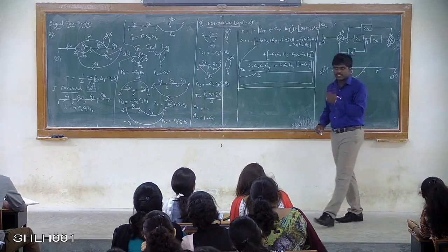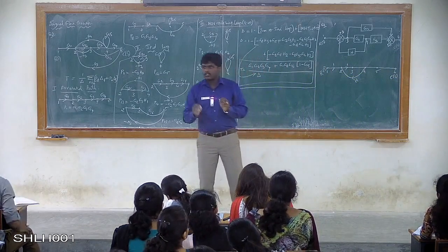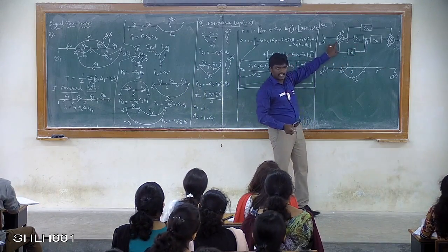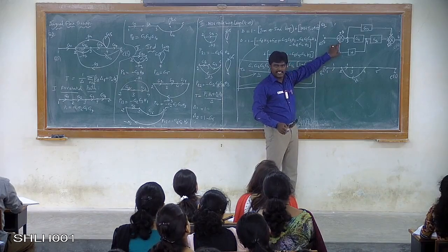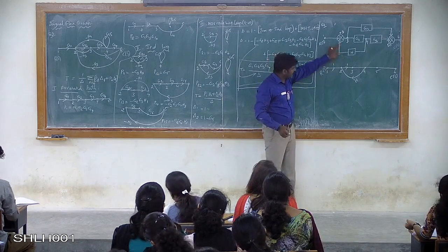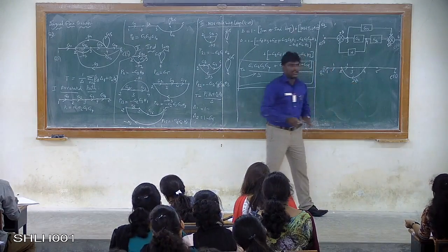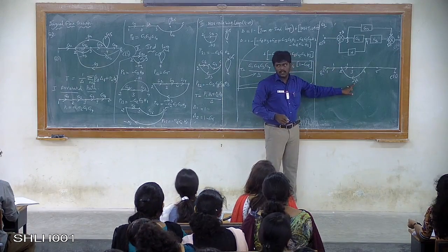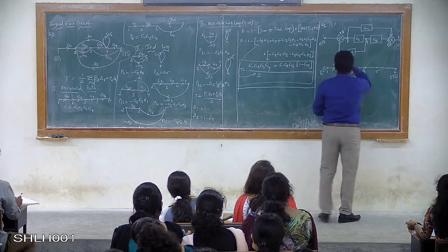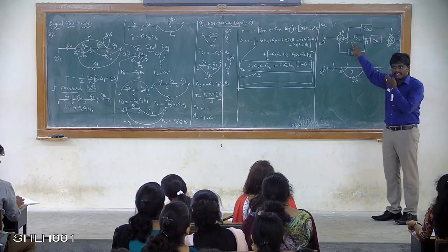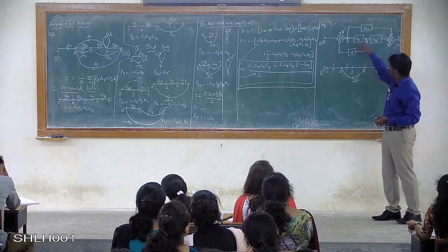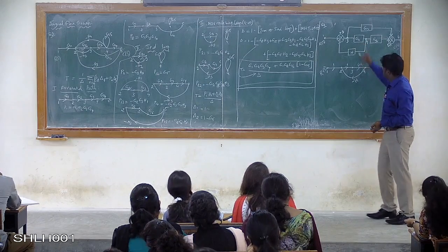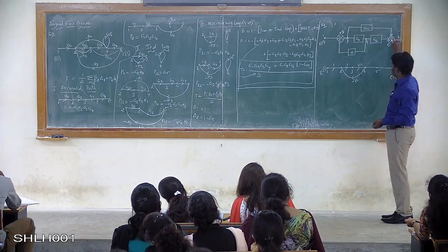Now, should the H be positive or negative? That also has to be determined. From 4 to 2, when it is joining at the summing point, what is the sign given? It is minus. So if minus is given, this H value has to be taken as minus. Got it? If it is plus and plus, then this H value will be plus H, right? So now we have finished with 2 also. Now go for the third one. From the third to 4, there is a direction like that. What is the gain value? G1, as well as from 3 it is also moving to node number 5.